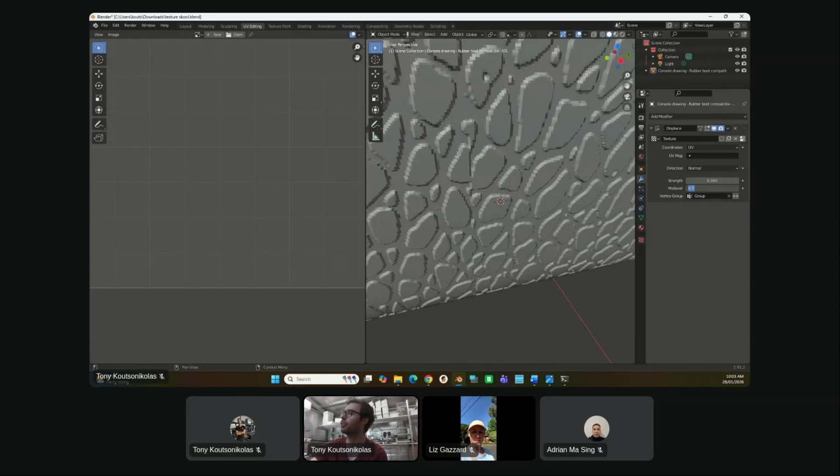With the only exception of, you know how we made the voxel size 0.2? You can see these tiny little increments. And that's because we're editing a mesh, all those little mesh points. And the smallest size is 0.2. So we're going to have some sort of granulation. That's what we call it. But in this case, it's still going to keep the detail, because you have to think about how we're going to make this. We are making this on a 3D printer that has a 0.4 millimeter nozzle. And when it goes around these corners, it's going to make them smooth anyway. Those are rounding errors. We are zoomed right into it, so you're not going to really see it at this size. But if you really wanted to be finicky, you could make the mesh even finer, but you're not going to see those little points.